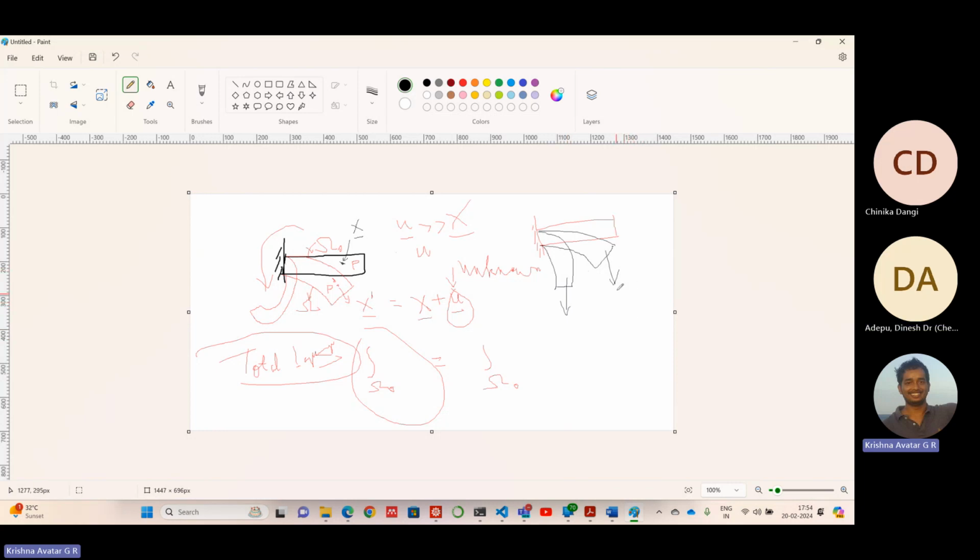We don't remesh it. What we do is we just update the reference configuration. When we move from here to here, we'll update everything and carry out all the integrals in omega. And omega will keep on changing. This omega is first omega, then omega 2, likewise, till we obtain the final equilibrium shape or equilibrium configuration, say omega n.